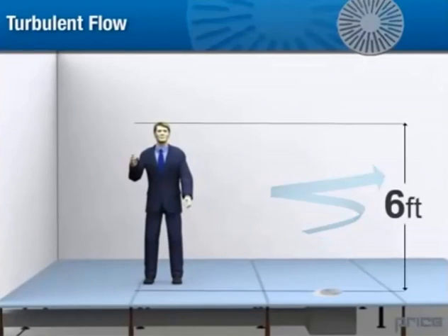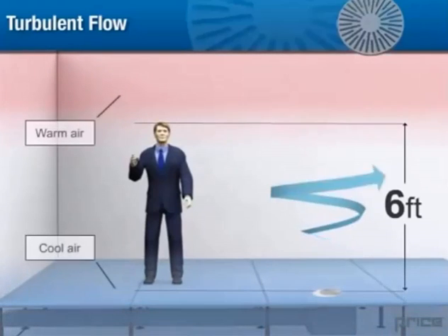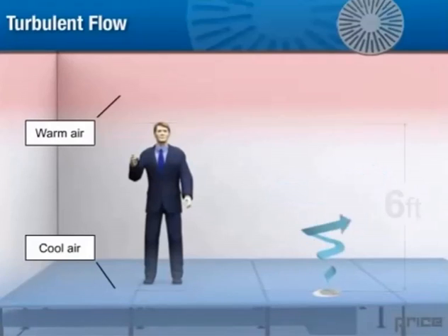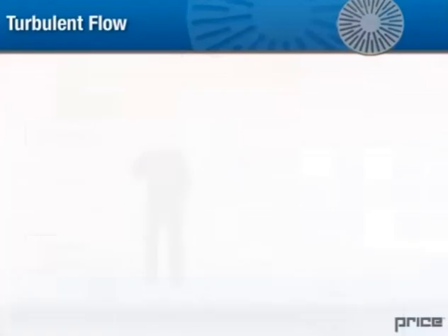In a properly designed underfloor air distribution system, the supply air should be fully mixed with the room air within 6 feet above the floor, forming a stratification layer at this point. This way, heat and pollutant collects at high level and conditioned air remains in the occupied zone.